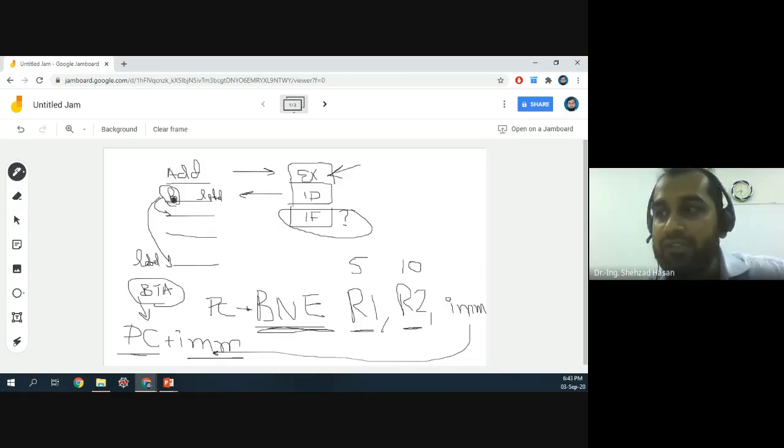If it's a taken branch, then it has to jump, and then you should execute this particular instruction from the right cycle. But the problem is that for branches, it's quite early to determine which should be the next instruction. What the branches can do in an easier way is fetch the next instruction, which the pipeline was doing earlier as well. It was always fetching the very next instruction and then moving ahead. It's going to bring some instruction into the pipeline. We don't know whether we have to execute that instruction, and then we are going to move ahead.